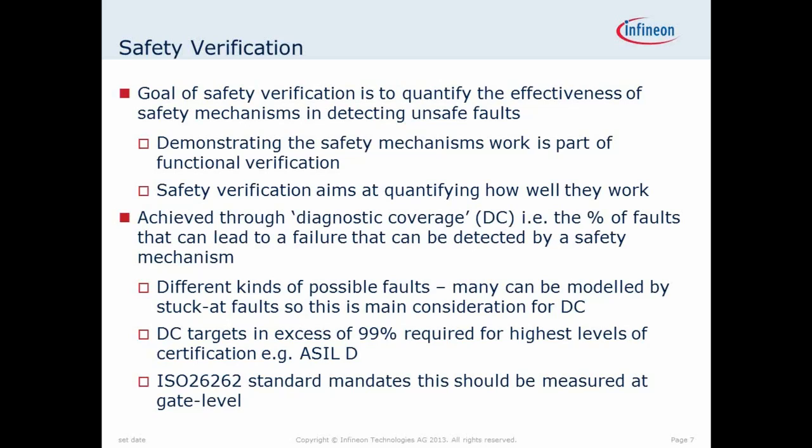In safety verification, you're interested in how many faults actually propagate to the outputs of your CPU. So how many faults inside your CPU actually propagate to a safety mechanism? How many can you detect? So it's a quantification process. The way you quantify it is through something called diagnostic coverage, and this simply measures the percentage of faults that